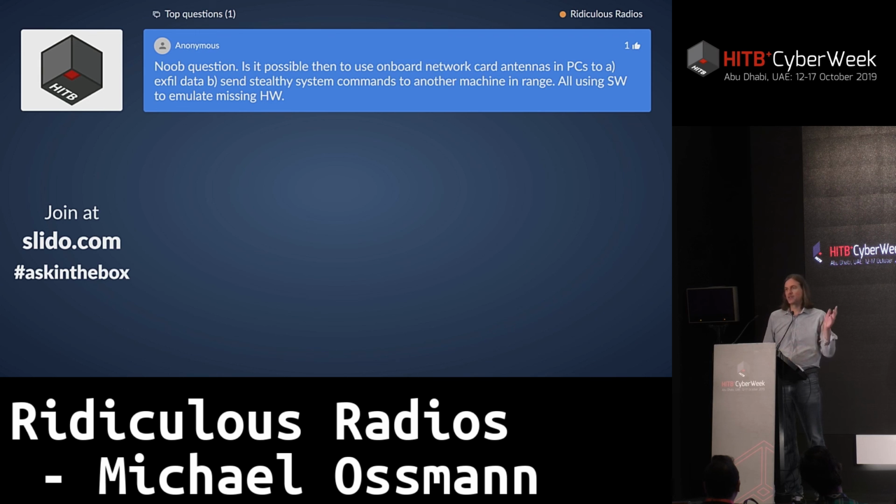And we would be transmitting on-off key data in the 2.4 gigahertz band that would not be detected by a Bluetooth sniffer, for example, because it's not a Bluetooth modulation. So it is absolutely possible in certain cases that you could, from software, reconfigure a device to produce a radio signal that is not standard, not going to be easily detected by equipment that would detect the signal that normally that device would produce.